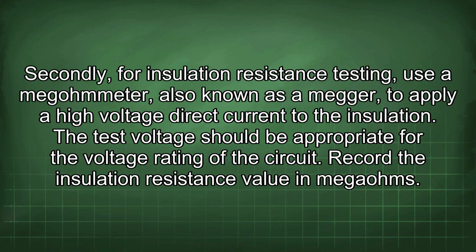Secondly, for insulation resistance testing, use a megohmmeter, also known as a megger, to apply a high voltage direct current to the insulation. The test voltage should be appropriate for the voltage rating of the circuit. Record the insulation resistance value in megohms.